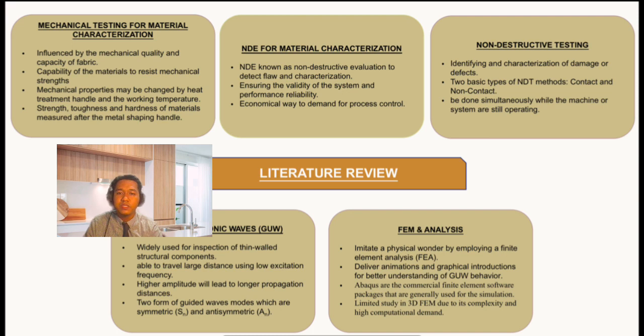The third one will be non-destructive testing. Non-destructive testing is a process of evaluating the material to find its characterization or to detect the defects according to a certain standard without changing the original property or corrupting the object under testing. One of the advantages is NDT can be done spontaneously while the machine or the system is still operating. NDT also can be divided into two, which are contact and non-contact.